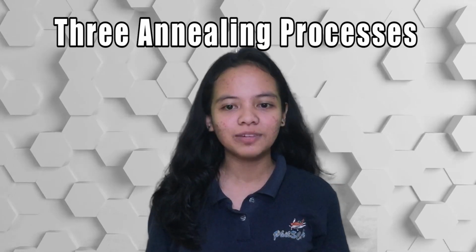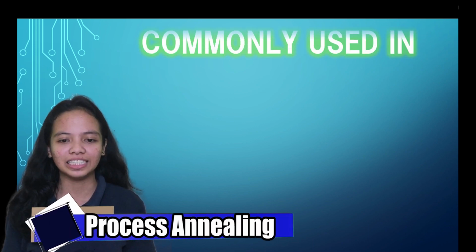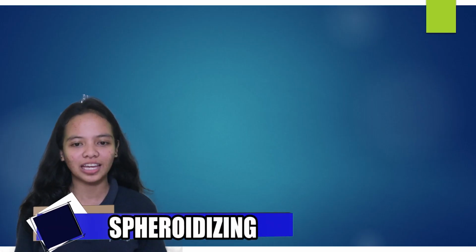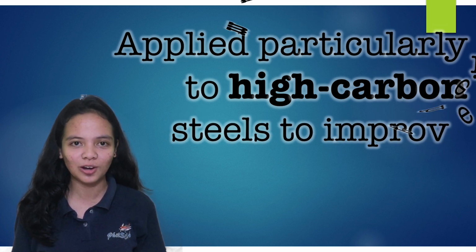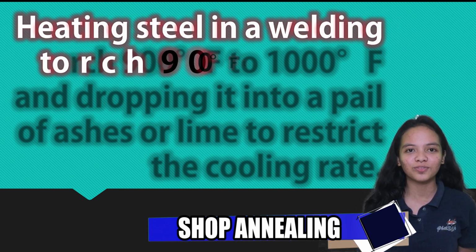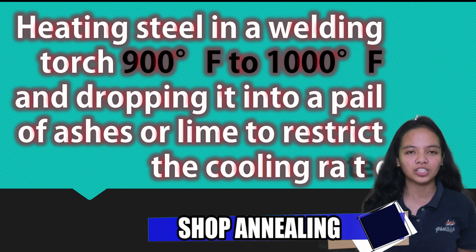There are 3 annealing processes used in ferrous metal. First, process annealing, commonly used in sheets and wire industries to restore ductility. Second, spheroidizing, applied particularly to high-carbon steels to improve their machinability. Third, shop annealing, heating steel with the welding torch to 900 degrees Fahrenheit to 1000 degrees Fahrenheit and dropping it into a pail of ashes or lime to restrict the cooling rate.